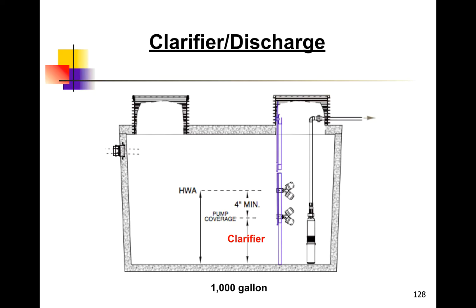So what that means is if you've got a high water condition and you're concerned about tanks flooding, you can actually raise these floats up, again, keeping them 4 inches apart, up to the point where the top float is just under the invert for the inlet of the tank. And that will maintain a large volume of water in the tank for ballast. Having more volume in the tank is actually a better thing. Again, we don't need emergency storage in this tank because a high level here will shut off the recirc pump, and our emergency storage will be accumulating in the 1,500 gallon tank.